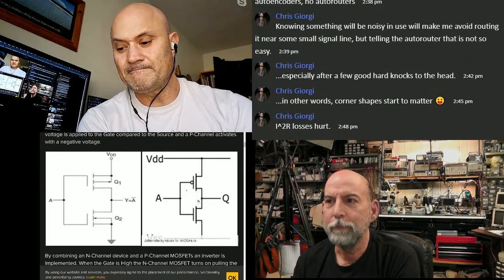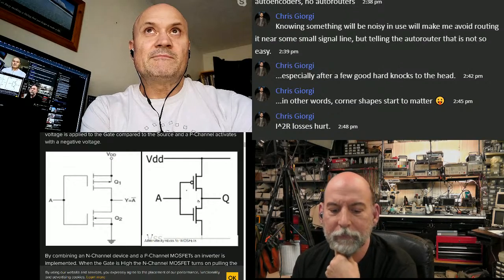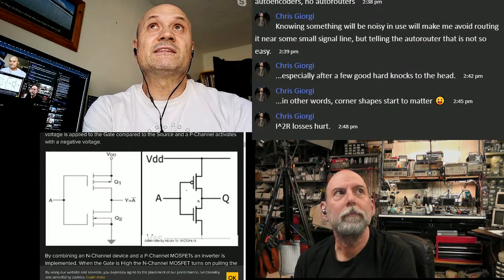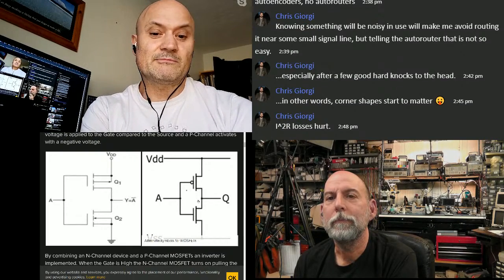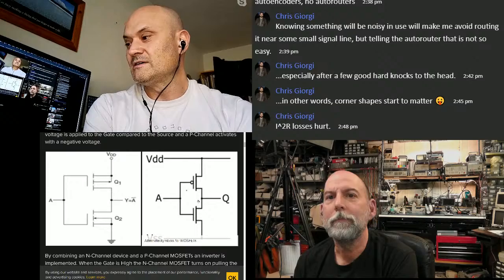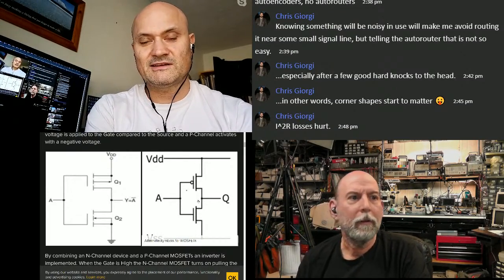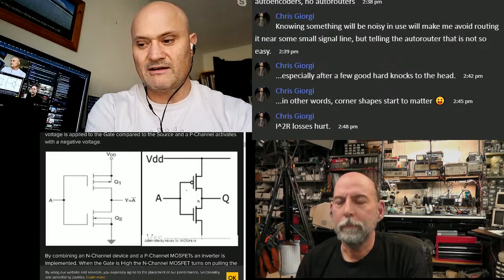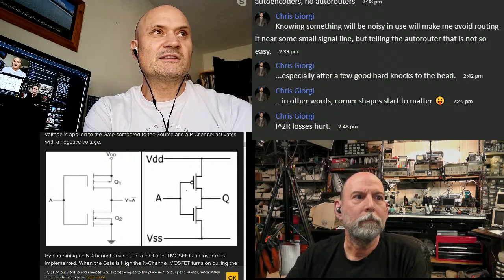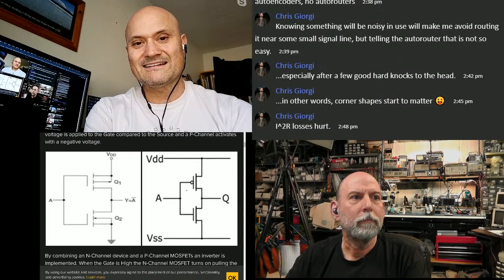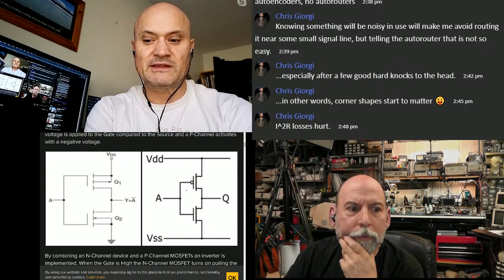Right. So there's no real easy way around that, and I'm kind of hoping that, because 90% of what's on your board is probably, unless you're designing a backplane, if you're just doing a normal industrial PCB design like most of us would be, only some of it is high speed, or only one portion of it is going to be RF or whatever. So I'm looking for a fab that can selectively polish or do things like that, where most of it's normal, but just that one bit that matters has been made smoother.